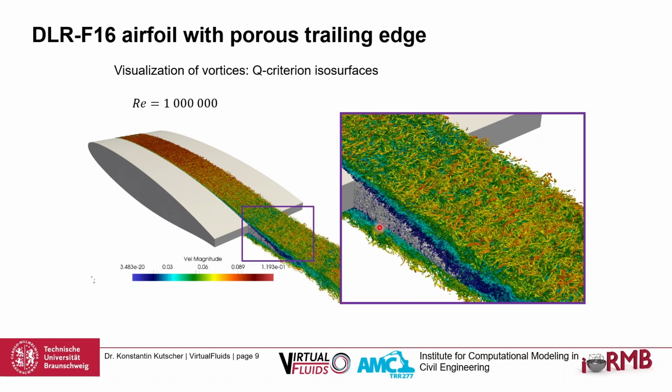We resolve this boundary layer and the porous flow inside the porous media. And another challenge was Reynolds number 1 million. It's a very turbulent flow. You have turbulent flow on the surface, and inside the porous media laminar flow, which is typical for porous media, because we have these pores, and the principle is Darcy flow inside porous media.